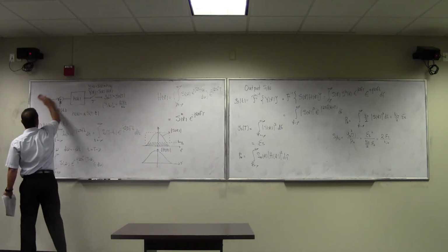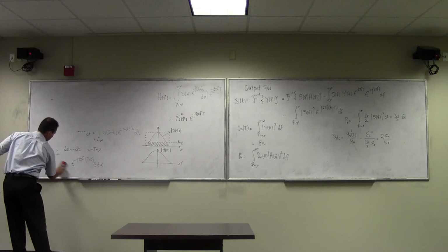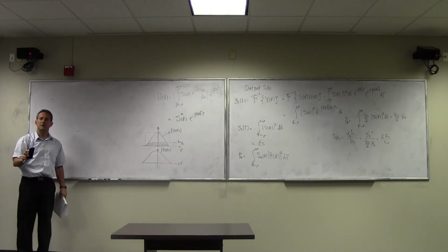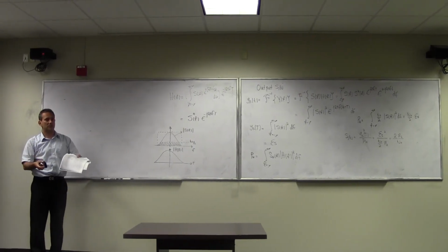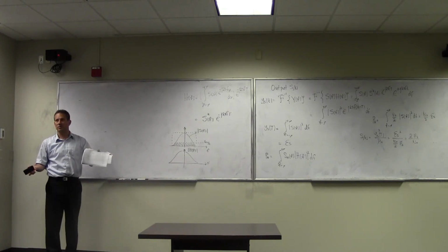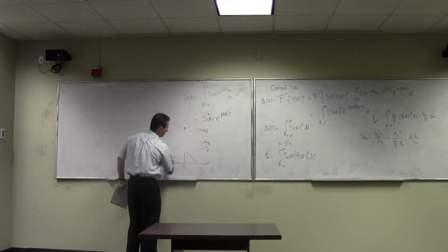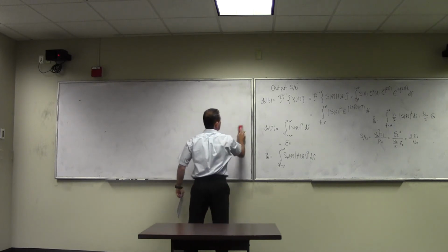Let me go back and refresh your memory on how we receive digital signals. You can see the reception is essentially two steps. First step is demodulation, which is projection of your incoming signal along the direction of the basis vectors. We do that through correlation of the signal with the basis vectors, which we now understand as filtering with a matched filter. And not only do we understand that this is equivalent to correlation, but we also understand that this is the best you can do in terms of signal-to-noise ratio maximization. After that, we have to look at what came out of these matched filters and make a decision. And this is the second step that we call detection.